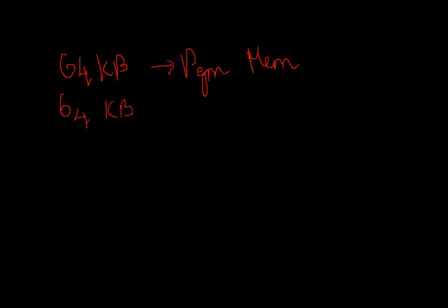The second half of this video is regarding the memory organization of 8051, which is yet another important topic, because without knowing the memory organization of any processor or controller, it is hard for us to code it up. So we totally have 64 kilobytes of program memory, and also 64 kilobytes of external data memory.